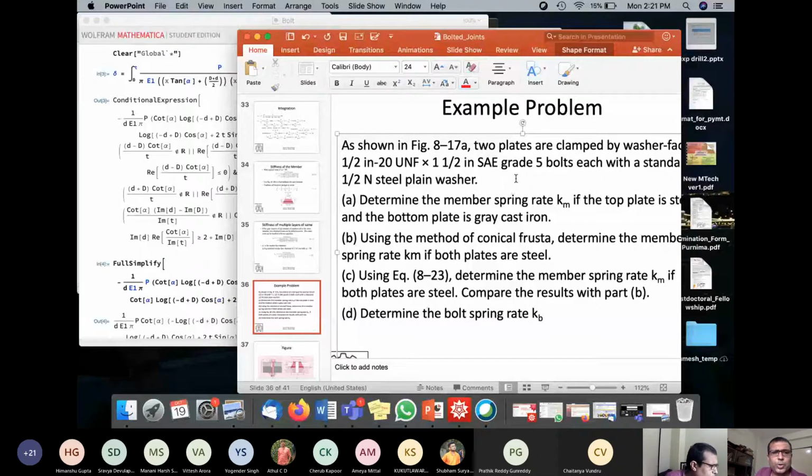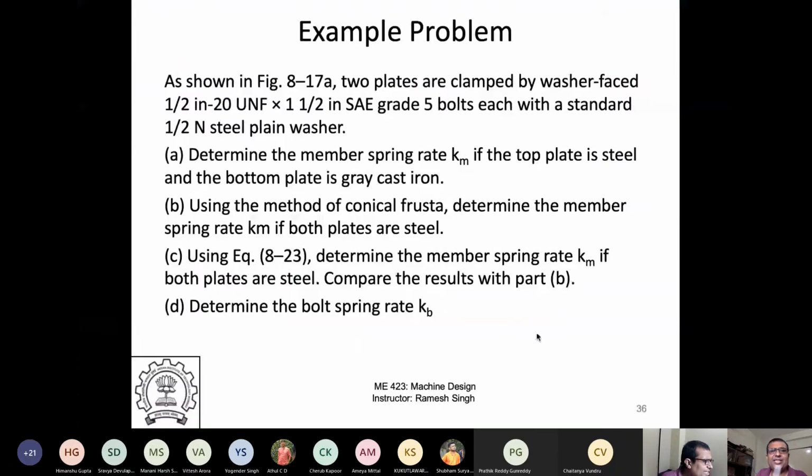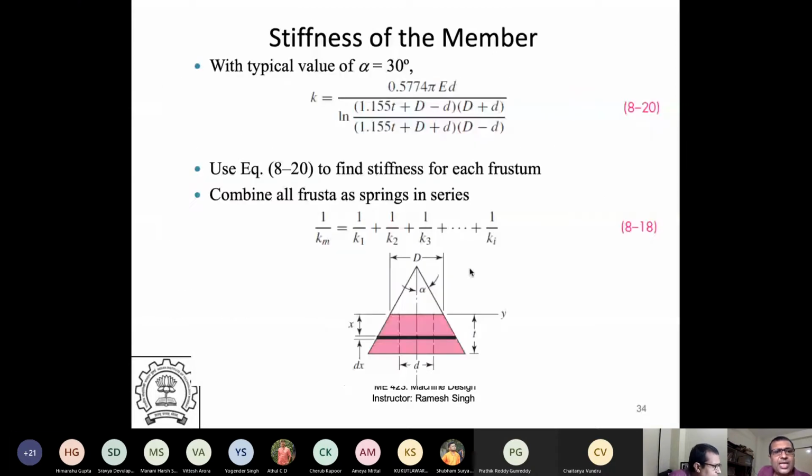Let me show you. There are some sizes which you will get. For a 0.5 diameter, you will get 1 inch, 1.5 inch, 2 inch. You will not get all the lengths. Of course, you can grind it and make it whatever size you need. But let me first show you that. I wanted to look at whether there are specific sizes, and I think this gives you that idea. But you can get any length of bolt. That is a variable. Probably it depends on the diameter, some multiple of the diameter you will get. This is something somebody was asking.